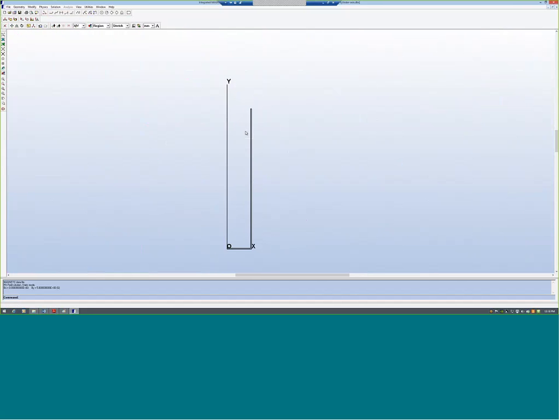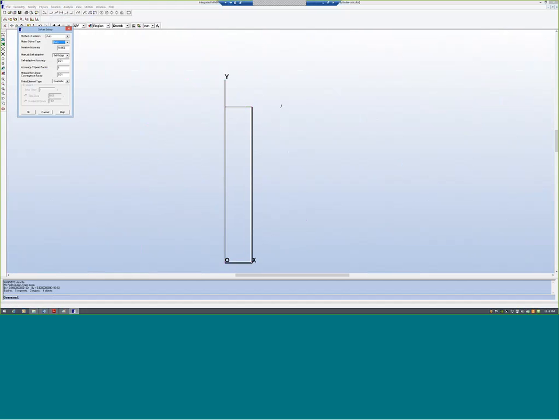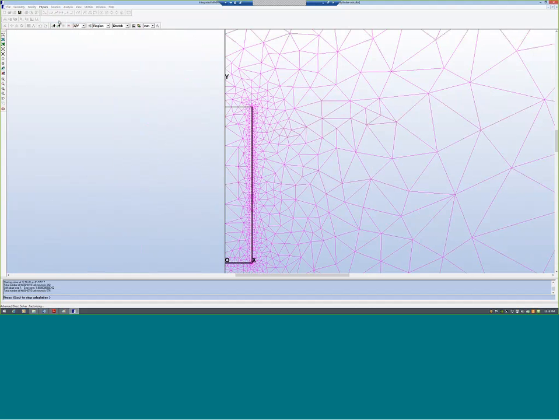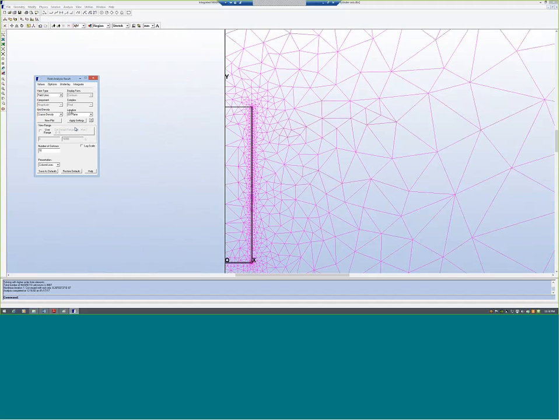Okay, to see the fields inside, it is comfortable for us. Let's see here. I want to draw this line, another region I'm creating, so that we can confine and see the fields here. Solution, solver setup, it is automatic, everything here. Of course, 2D models are at least maybe 1,000 times faster than the 3D models. That's all. You've got the result. So this is almost instantaneous.